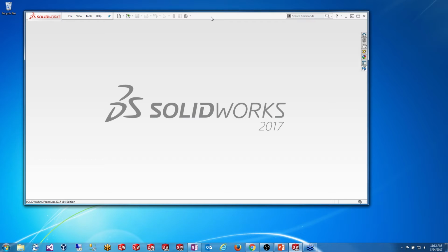So with the PDM system, you can be very specific about your permissions. So you can say, I only want certain people to have certain access at certain times for this file. Maybe when that file is in an under editing or work in process state, maybe I want to give everyone access to make changes to it, and then kind of lock it down as it moves through your workflow and finally gets approved. But let's say maybe you want to send that file out of the vault, or you really want to be sure your manufacturing doesn't take that drawing and run with it if it hasn't been approved. So you want to make it really obvious to everyone viewing that file, or even if it gets printed out, that file is in a work in process state.